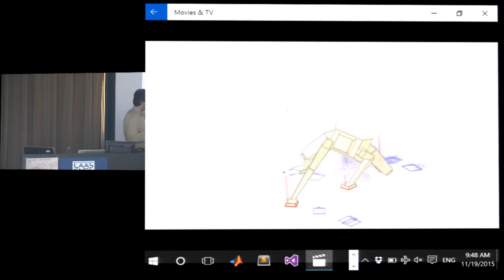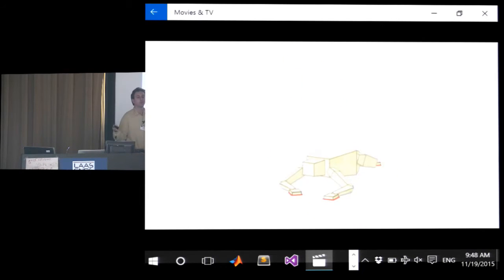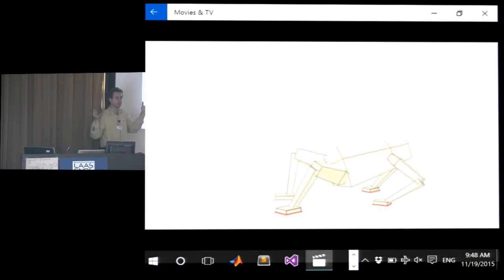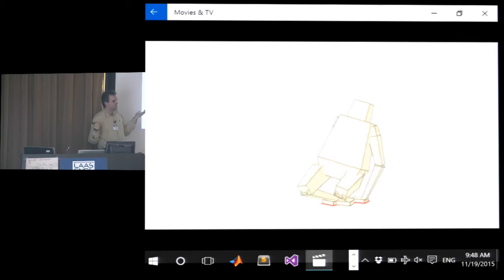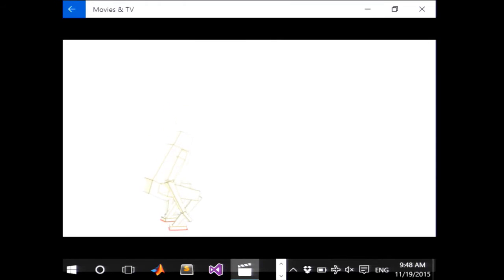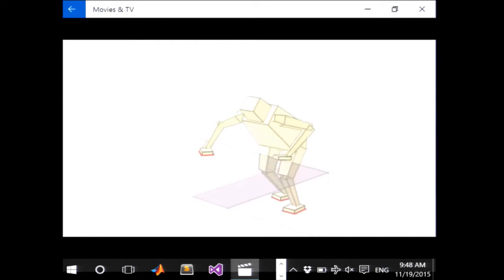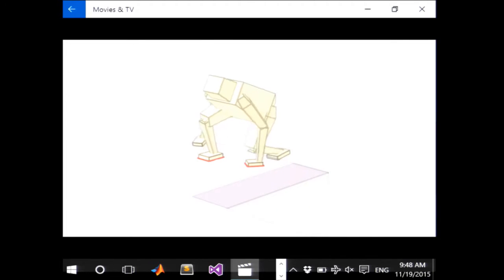So everything I'm going to show you here, the entire movie is the optimization object, basically. We're optimizing the sequence of poses over time and the sequence of contact forces over time as one big object. So it has like several thousand variables in it. It takes on the order of 5 minutes of CPU time to generate one of those. So the cost functions are really simple. So there's a cross here. The cost function says, start at the given initial condition, put your body over the target, and minimize accelerations of the joints in this case, I think. Okay? And all the details of this come from the interaction between the physics and geometry and your optimizer and this really simple cost function.